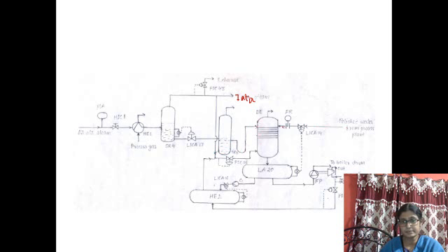This is from the source, and this is the recycled water. This is called reutilization. So water is sprayed from the top of the deaerator tower, and from the bottom of the tower 7 atm steam is sent. So there exists a pressure control loop, and in order to check the level of the separator,